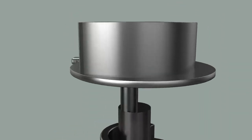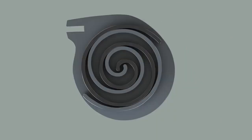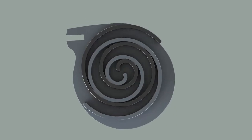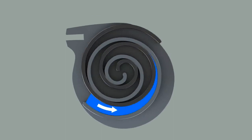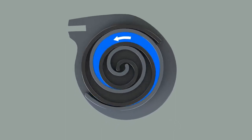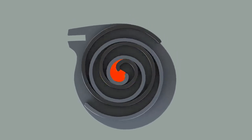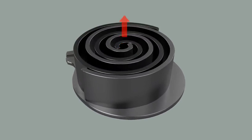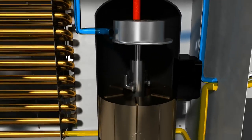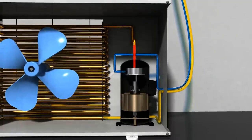However, more air conditioners nowadays use a scroll type of compressor rather than piston type. In a scroll compressor, there are two scrolls of which one is fixed and the other rolls constantly. As more air coming through the entrance gets inside the scroll, space becomes crowded. As there is less space now, gas becomes more compressed and is discharged from the middle of the scroll in a compressed state. The reason for using such a type of compressor is the efficiency of space utilization. This type of compressor allows the machinery to become smaller in size and reduces noise as well as vibration.